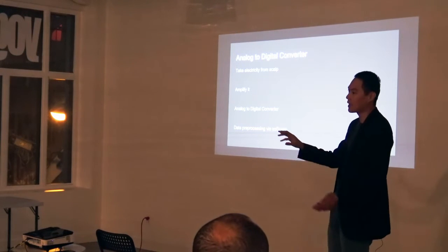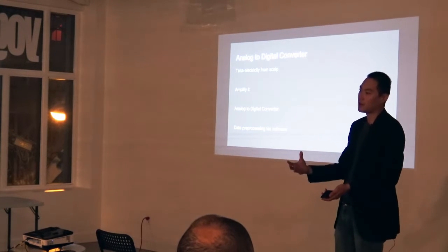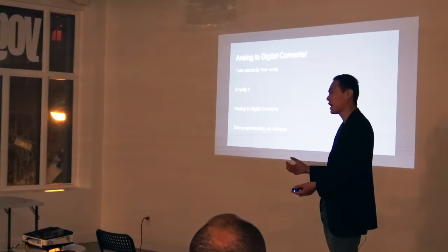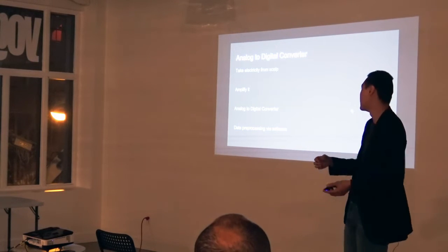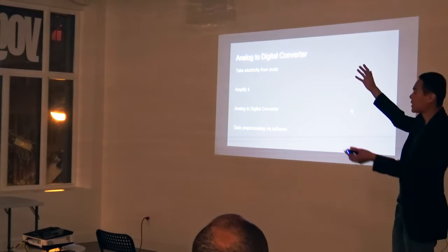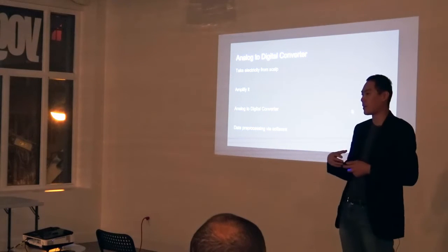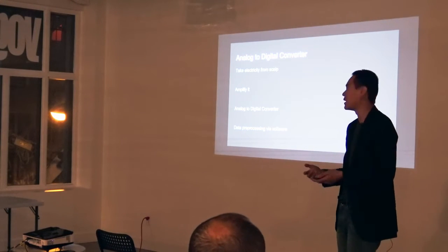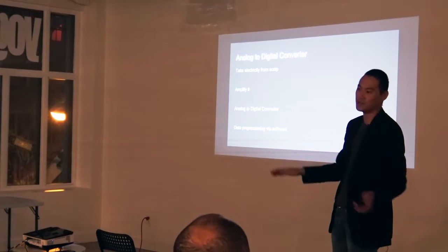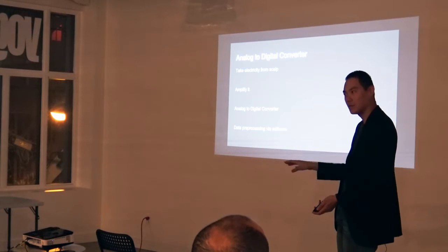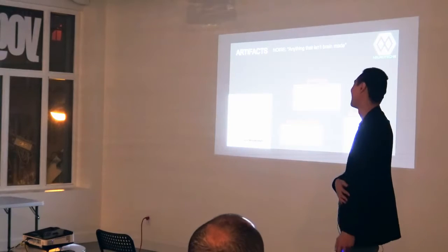So in a nutshell, we're taking the electricity from the scalp and amplifying it using on-site hardware. Some other primitive but also useful BCIs like EEGs don't have an active amplification system. It's not a bad deal; it depends on how well it's designed. Basically, we take the raw signal, amplify it, and turn it into a digital format, and then we can start to work with it in software for data analysis and, more importantly, pre-processing. Because raw EEG data is really useless. But after you apply a few filters to it, it becomes more useful than useless, I'll put it that way.